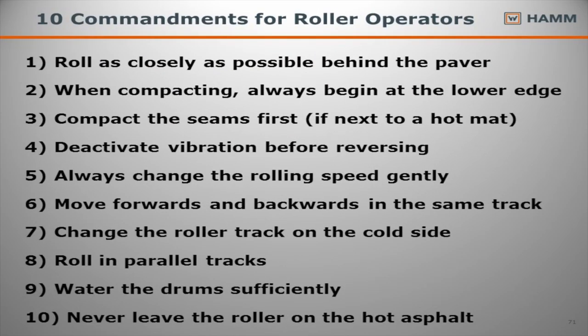So, 10 commandments we look at. Roll as closely as possible behind the paver, but do not hit the paver. There's a lot of guys that break down rollers, they try to come up as close as possible to the paver and just touch it and then go back. Number one, it's a waste of time. And number two, it's a safety issue. A huge safety issue, because a lot of times the guys on the street aren't paying a lot of attention, and if they walk off, that roller's not moving.